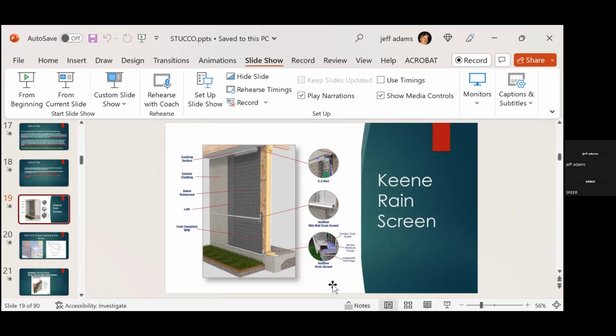Again, it's drying out these stucco walls, but by pulling in that fresh, cooler air down here, we are also going to make a big difference on our energy efficiency with these products. And hopefully one day we can get the code to require it behind every type of product, whether it's fiber cement, whether it's cedar, or anything that does not have that. Obviously, our masonry veneer already has that 1-inch air pocket back there that, when done right, allows air to move through there and works great for breaking that thermal bridging.